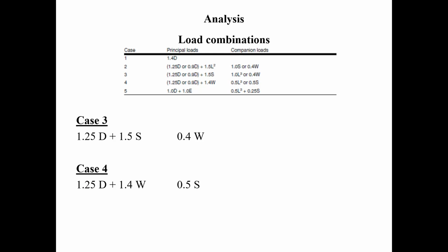First of all, you don't take case 3 for your deflection. You take case number 4 because it's higher than case 3. Oh, okay. That's number 1. Number 2, okay. Remember, for wind, the importance factor is 0.75 instead of 1. So what do you do to your W?